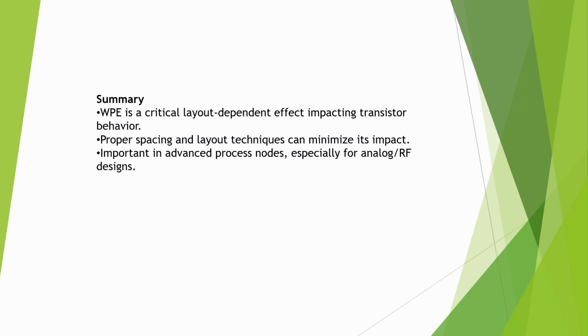So ideally, WPE is a critical layout dependent effect that impacts transistor behavior. Proper spacing and layout technique can minimize its impact. The main thing is we should not keep any device near the well edge. Second, we have to put dummy devices around it. Third, in analog layout we have to put a guard ring. It is important in advanced process nodes, especially in analog and RF. This effect is dominant in analog as well as RF design. So that is what we call the WP effect.